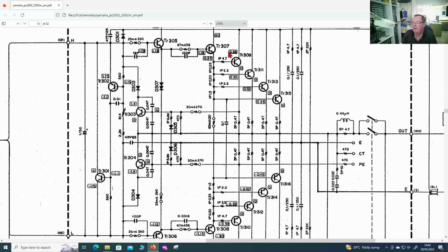So that's 0.55. Then look, we have a resistor, 0.33 and 3.3, different values. And this has 0.53, so this transistor is not as turned on as that one. And the same with this one, through another resistor, a different value again. And then the last one through another resistor, so that's all of these in series, less voltage again. So what that means is, when you start getting an audio waveform here, as the AC comes above 0, this will switch on straight away. So first of all, just this transistor is driving the speaker.